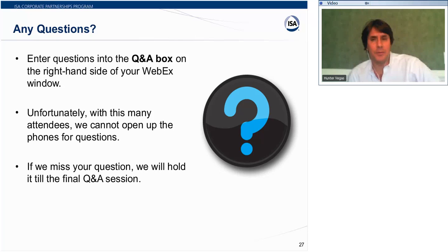I guess I'll take that one too. I mean, it's any differential pressure transmitter, whether it's on a steam drum or level or whatever it is you're doing. In order to calculate the calibration, you have to understand the 4 milliamp point, the pressure the transmitter is going to see at 4 milliamps, and then the pressure the transmitter is going to see at 20.